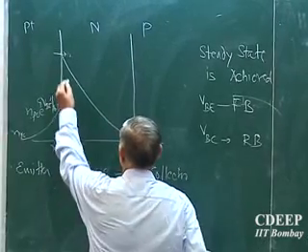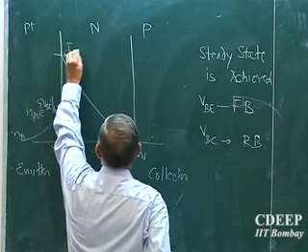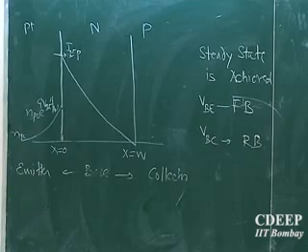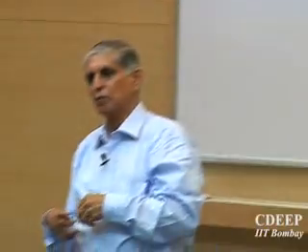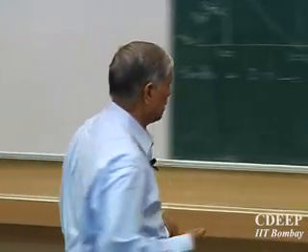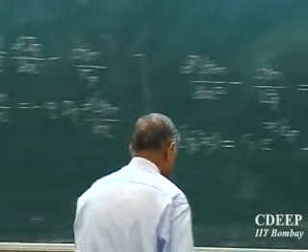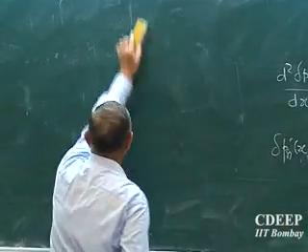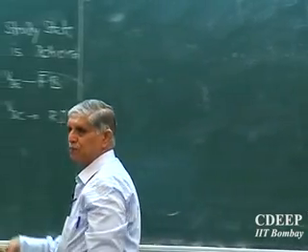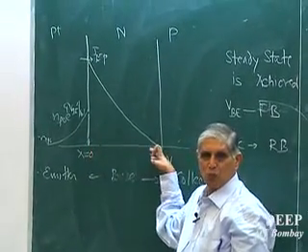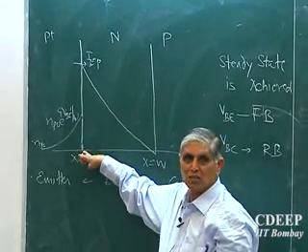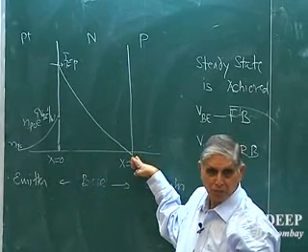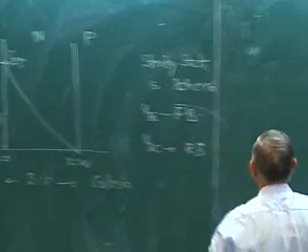So right now I am only interested in the current which is entering here, IEP, and I say if I know my gradient, then I can calculate the current at the base emitter junction. So now I have to get this equation solved, that is, for C1 and C2 to be known, I need boundary conditions. There are two boundaries. One is here, one is here. Please remember, this is the base emitter junction, forward bias. Is that correct? This is the base collector junction, reverse bias.